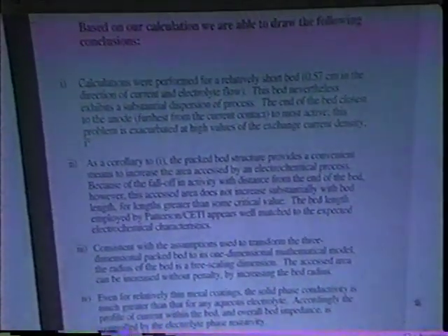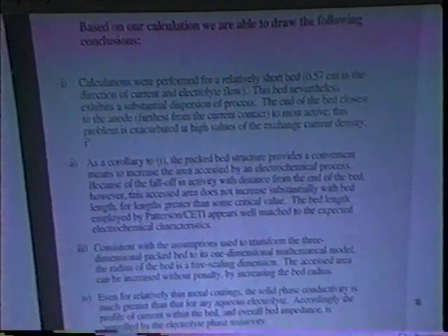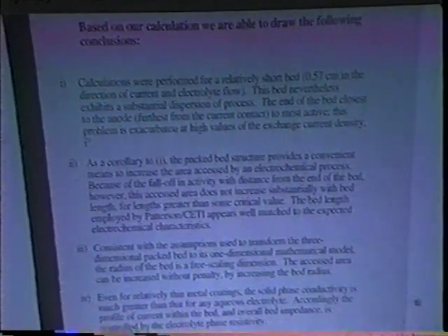draw some conclusions. Calculations were performed for a rather short bed, only 0.57 centimeters long. This bed, nevertheless, exhibits substantial dispersion of process. Only the top of the bed is really active. So extending the length of the bed doesn't buy very much at all.